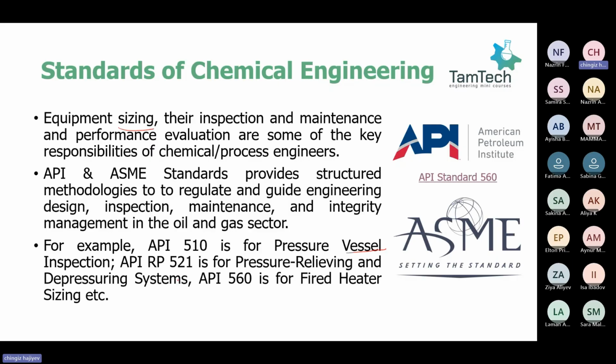If you want to know what overpressure is, where it can happen in which equipment, for example in separators, and how we need to regulate overpressure scenarios, all of this is covered in these types of standards. API 560 is for fired heater sizing, and it includes how we need to size and how we need to maintain a fired heater.